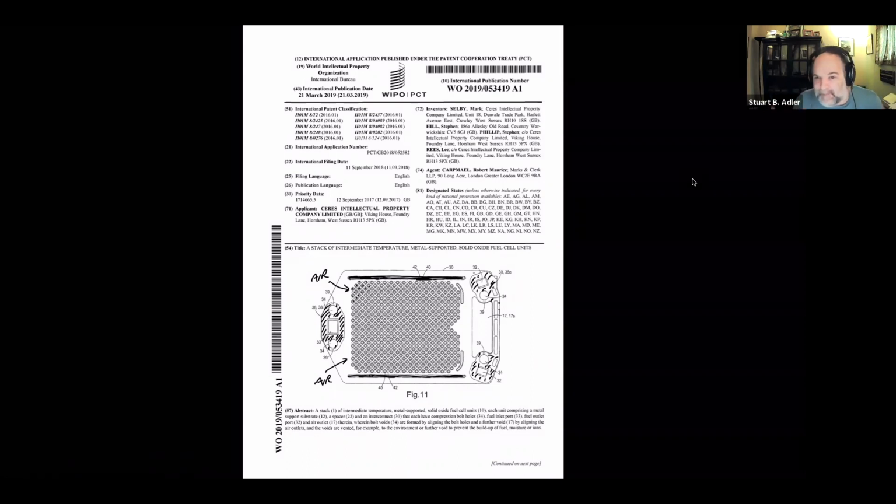And one of the other purposes of having a pin field like this is that it's like a porous media that the air has to flow through. So as the air flows through the pins, there's a little bit of pressure drop, creates a little bit of resistance, and it makes the flow of the air more uniform than it would be if you didn't have any of those features present. Sort of like, if you make espresso, you pack all the coffee in and drive the water through it as a packed bed that has pressure drop, that forces the water through at a fairly uniform rate wherever you are in the filter bed of your espresso.